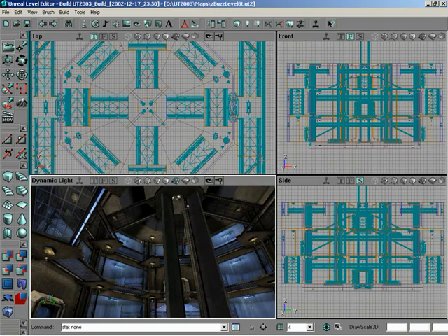And finally, after we go in there and use brushes so that we can do subtractions and adding stuff in, and we bring in static meshes, and if we were to use any terrain, and we start placing various actors all over the scene, and our lights and our textures, and all that stuff's out of the way, then we've got to do a thing called rebuilding, isn't that right? Right. So what is this rebuilding? Rebuilding is where it takes the current position of your brushes and your lights and recalculates stuff like where the actual geometry is and how shadows are cast from those lights. Okay. So once all of this is complete, then you can actually go and play the game, or play the level, that is. Okay.